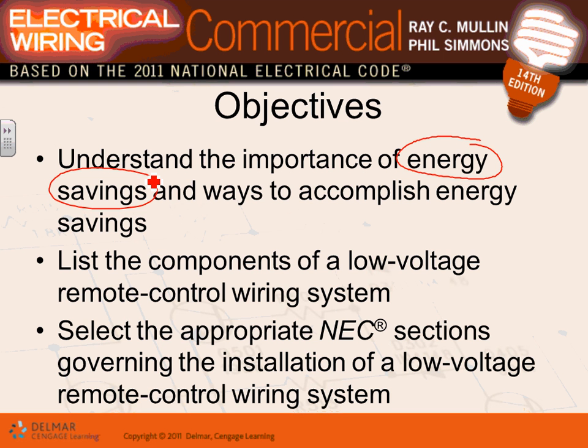Okay, components. What is a lighting control system made of? So we'll talk about the brain. You guys have seen a lighting control panel. There is a brain that controls all these relays. You program this brain and make it turn them on and off at certain times, get inputs from occupancy sensors, low voltage switches, and a bunch of other things.